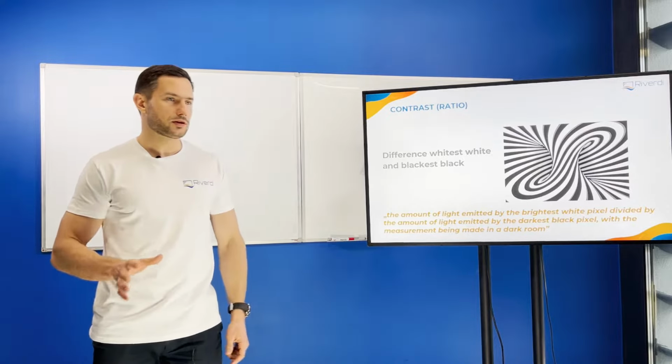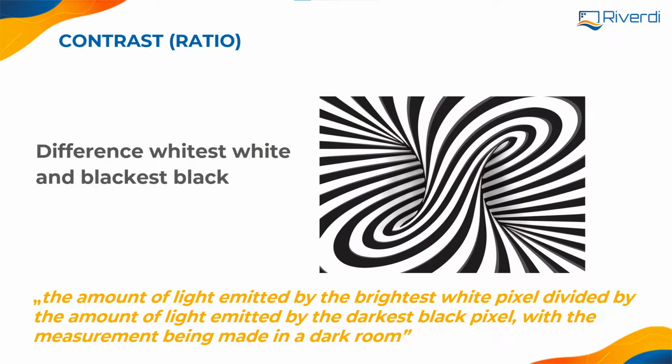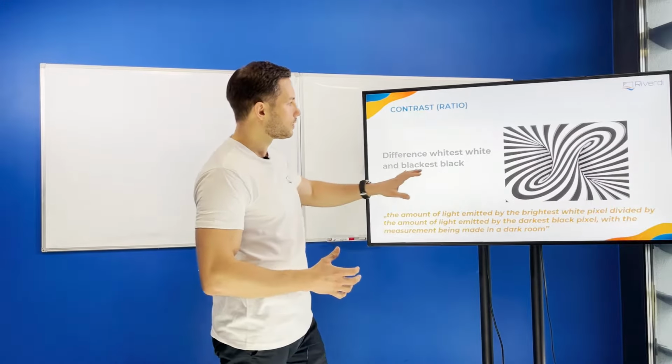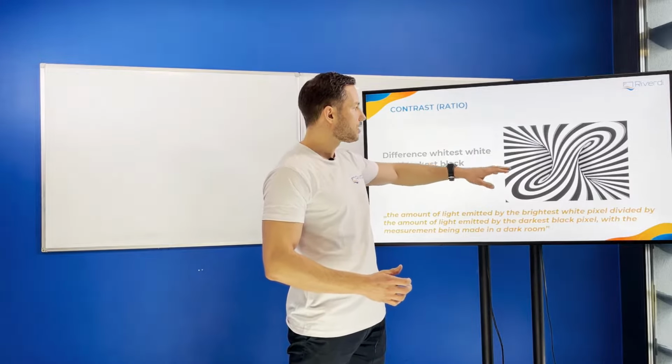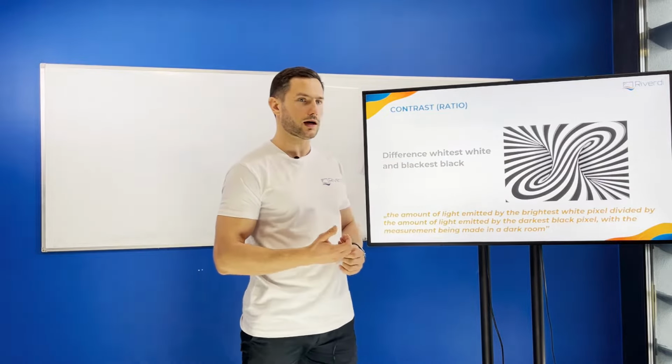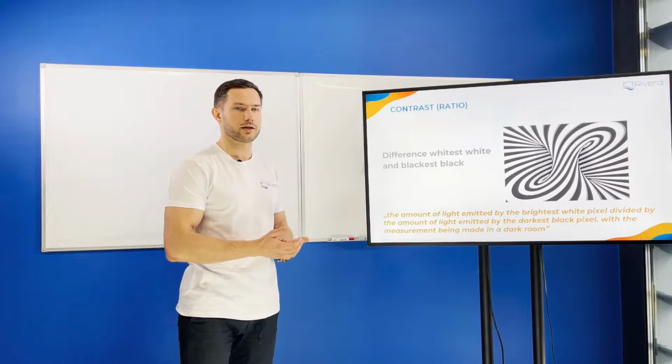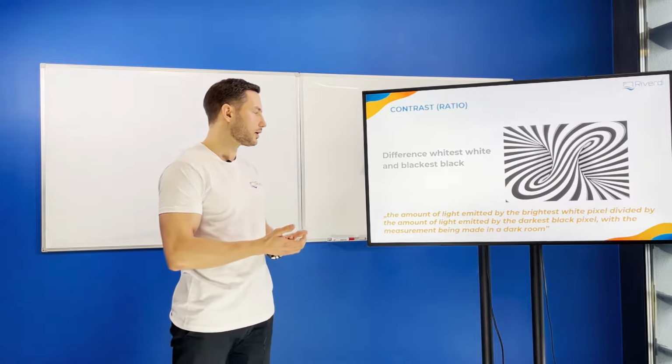So basically, first thing, what is the contrast? It is just the ratio between the bright parts of a display and the dark parts, yes? So this is pretty simple to measure. We just measure the brightness. If we imagine this is a display, we can measure the white part, how many candelas there are. Let's say it will be a 1,000 candela display or something like that.